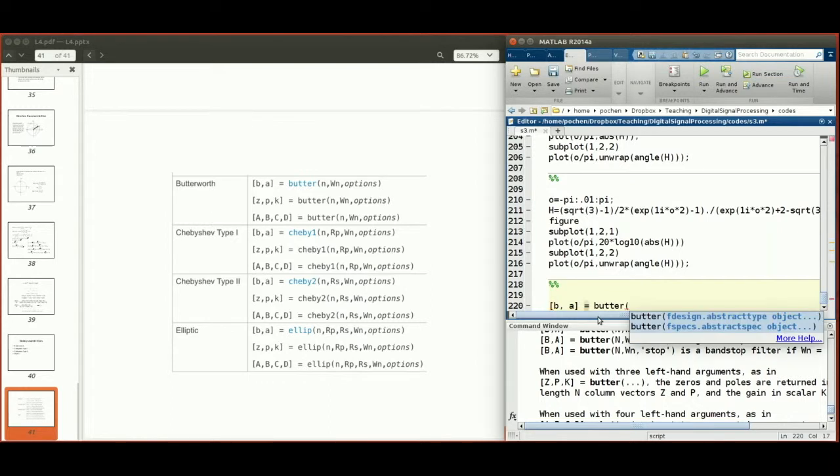So let's try a 7th order Butterworth filter. If you increase the order, then you'll have more poles for the filter. It's going to be more expensive to apply the filter, but the benefit is that the filter is going to be a more accurate approximation to the desired filter. Here we're just using a 7th order Butterworth filter.